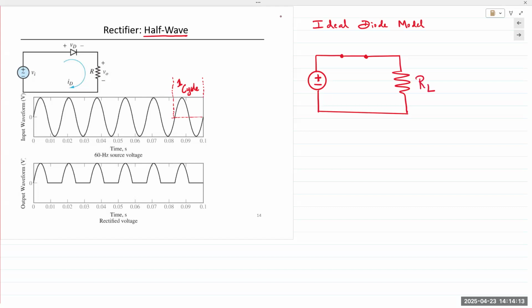This is simply the load resistor RL. Okay, simply a generic representation of the load. Load could be anything. And diode D1 is on, and current flows in this direction. Point of entry is from the top. This causes a voltage drop, plus minus, VRL. Make sense?